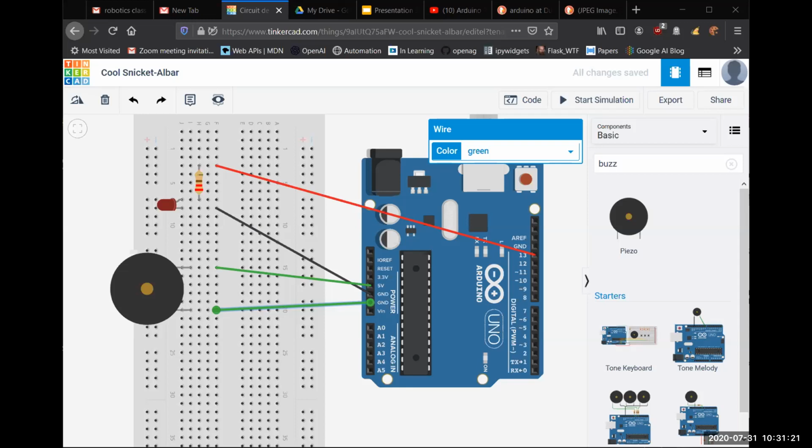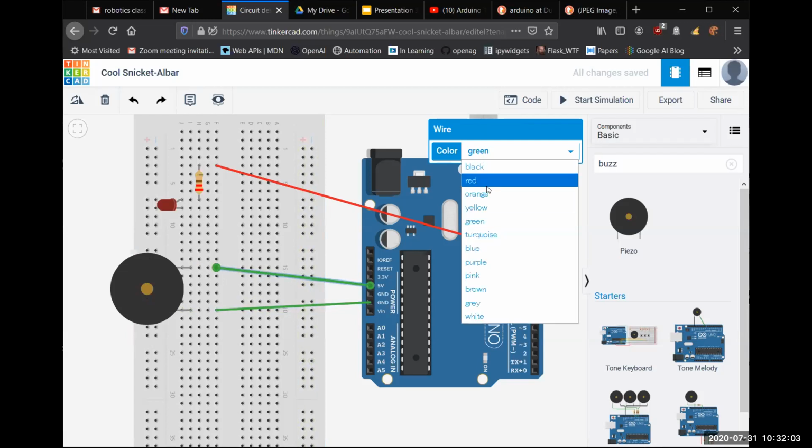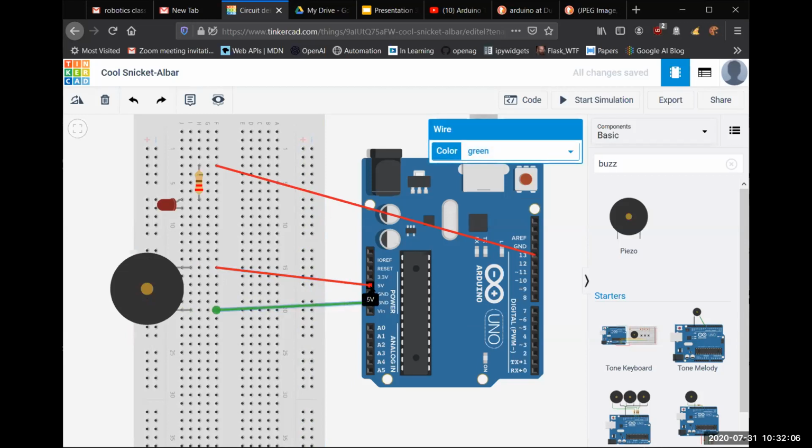Have you been able to do that, Leilani? Not yet. Okay, just do this the same way we had done the first LED, the first circuit, right? So you'll connect this side is positive, where it's written a plus here, and then the other side has no color. So you can use red wire here, and then the other one to be black. One you'll connect to 5V, and the other one you'll connect to ground, G N D.